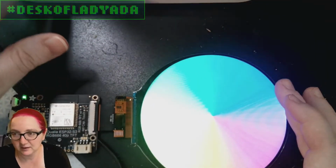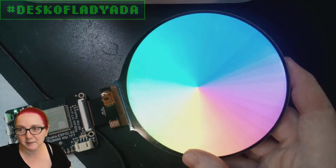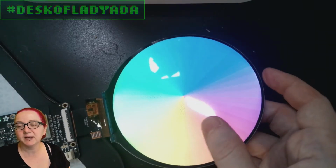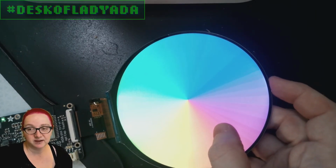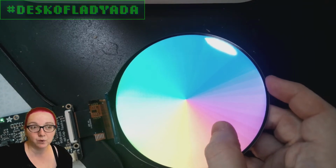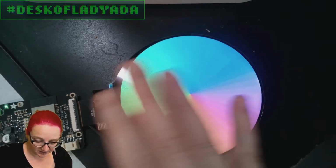So this is our ginormous 4-inch display. And you can see it's much more vibrant in person, of course, with this rainbow display on here. I will say it does flicker a little bit, and I think that's because I'm still in Arduino using IDF, like 4.4. In CircuitPython, we now use IDF 5, thanks to Scott. If you checked out his videos, he did an update to implement ESP-IDF 5.1 in CircuitPython. And one of the things that it improved was the RGB TTL display support is much more stable, greatly improved.